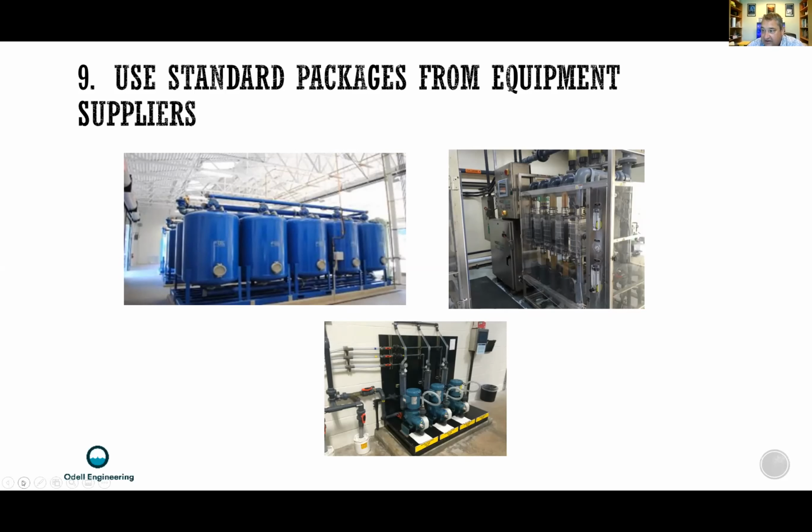that's what I like to put in a specification, and not too much detail on what the underdrain needs to look like or how tall the sidewalls need to be on your filters. Any of that customization by equipment suppliers costs a lot of money for them to change. So wherever possible, I like to try to work with their standard equipment.